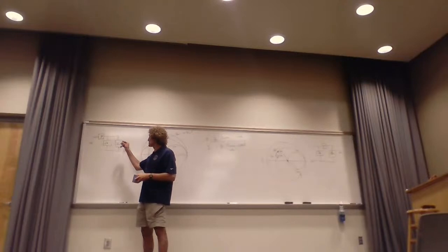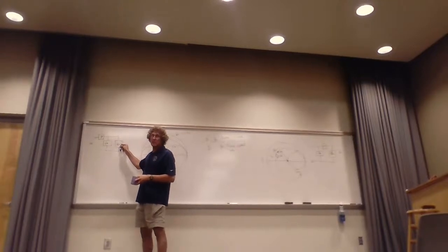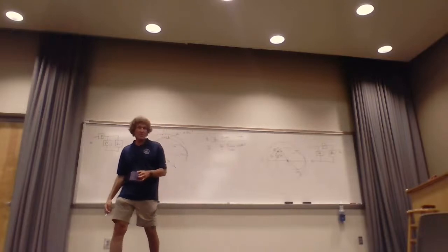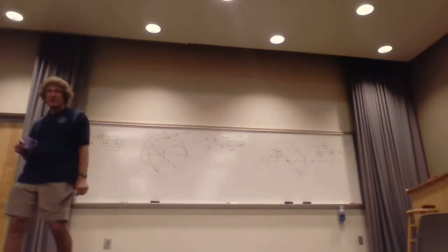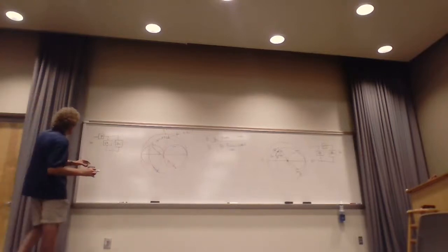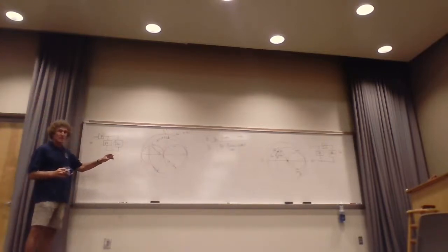The first thing is you're adding something in parallel with the load, right? So you get to the rim, and when you're at the rim and you add this, you match it. The first distance that you move is associated with some element. These are connected right to the load. I'm talking about on the Smith chart. The first distance you move to reach one of the edges, that change is associated with some element.